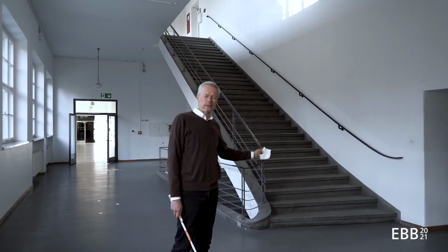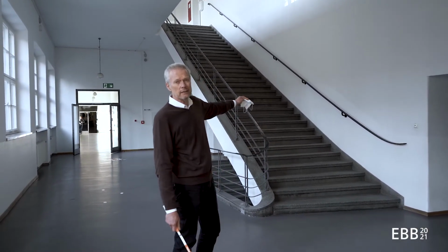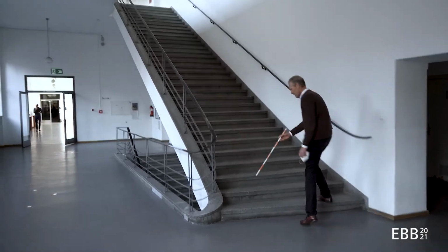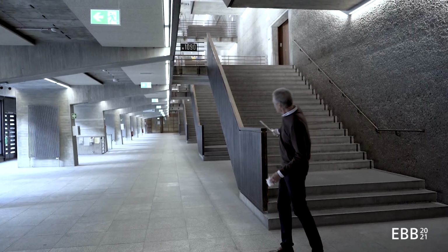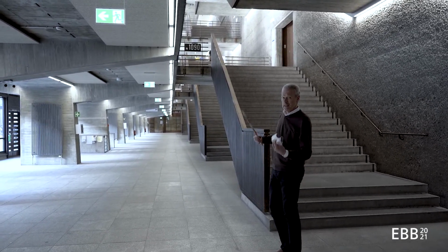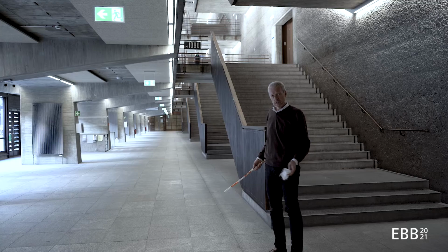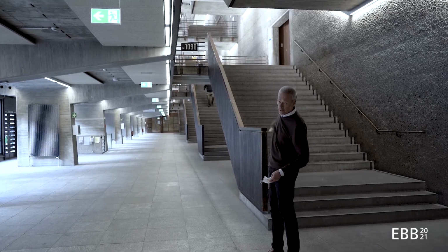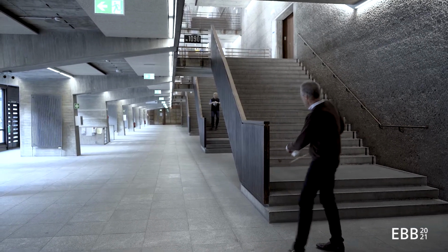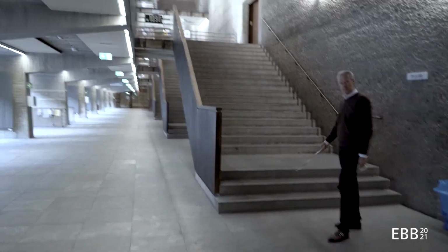So here I am next to a very dangerous stair. Why is it dangerous? Because it has more than 18 steps in one flight. Let's measure how the steps are. The steps are changing. So this number of flights of stairs is easily recognizable as leading to auditoriums, because we have to count in Germany 60 centimeters per 100 people in the auditorium. So there's a series of auditoriums behind, and thus we need several stairs of, I would say, 3 meters width here.